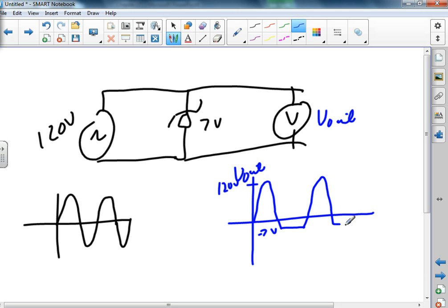So my Zener diode is throwing that power, if you consider that power, sending it to ground. Okay, throwing it away. Well, how do I do that? I do that with heat, right? So the only way I'm going to do that is that I can't just ground something out. It's going to have to be heating up the Zener diode. So in this application, I'd have a huge heat sink there, so that I don't melt this thing. But that's what it would do. It would cut off the negative voltage.